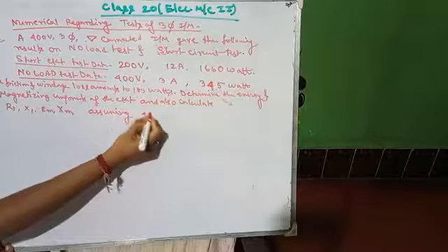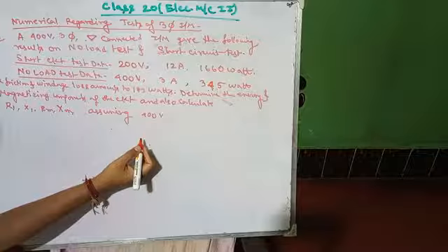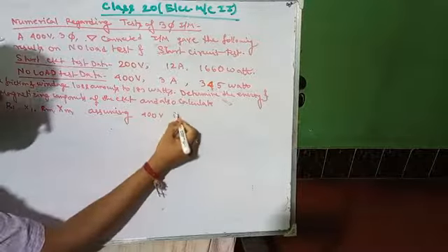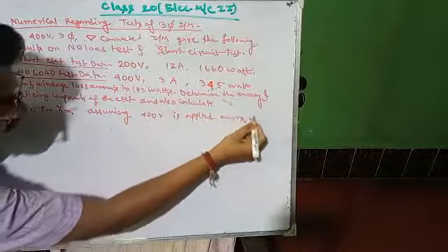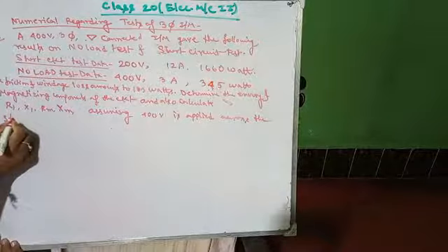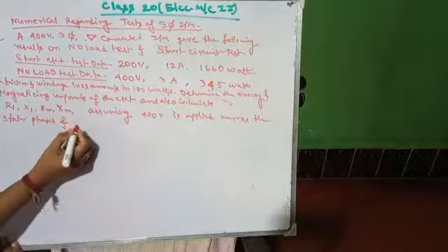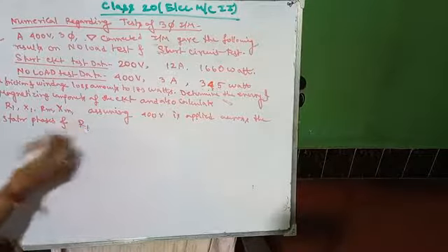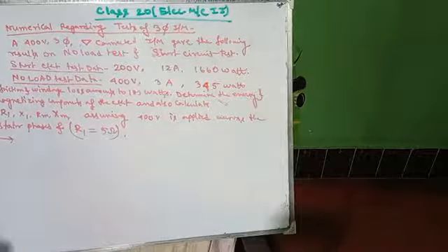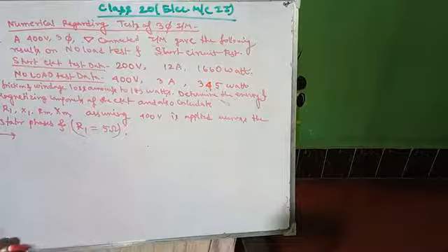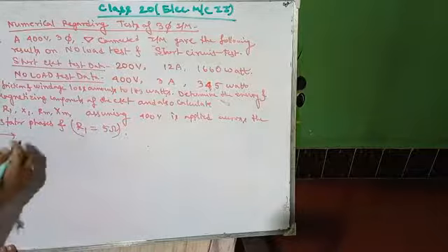assuming 400 volt is applied across the stator phase, and stator resistance, that is R1, assumed to be 5 ohm. This type of question is frequently asked in your exam. So now we have to perform the test, starting with no load.